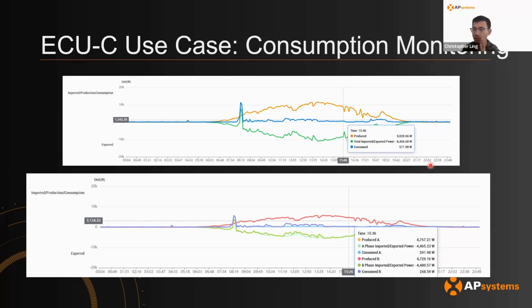You just have to give our team a call if you want to do something like that. The other thing also is to make sure that you use a CT that does not output voltage. It should be a current to current transformer type of CT. There are ones that output voltage, so make sure we use the current output ones.